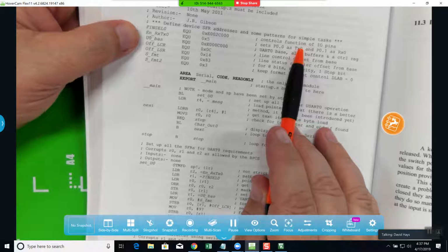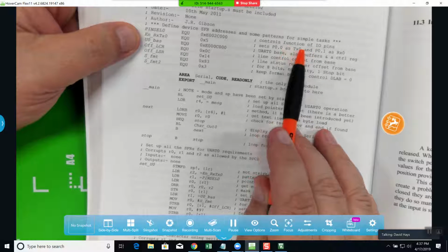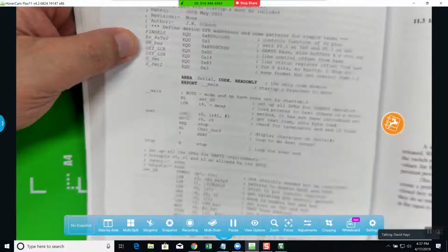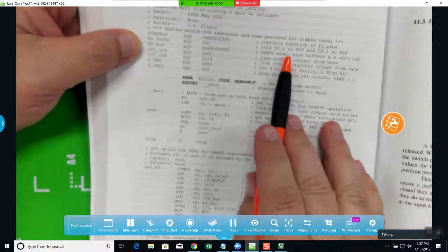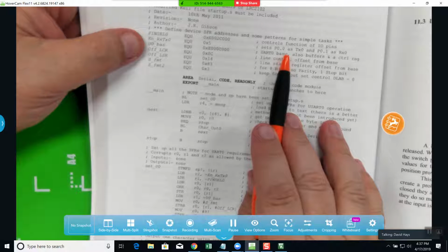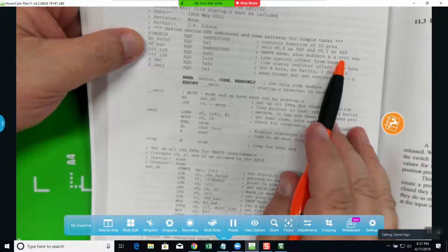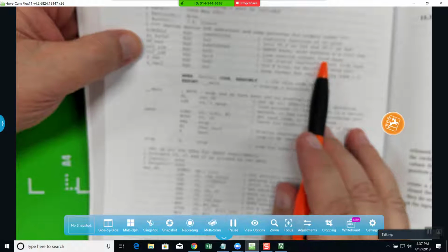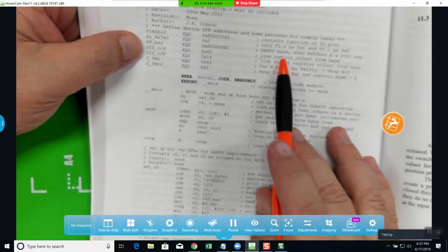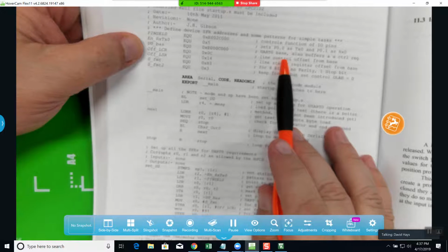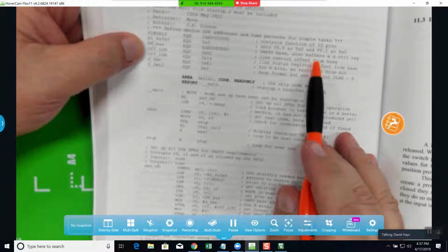Again, we're programming this to work with the pins, so it controls the function of the pins. Here it sets P0.0 as TX0 and P0.1 as RX0. UART 0 base, also buffers and control registers.